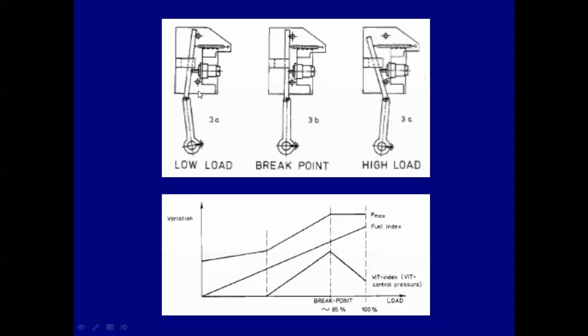So as this button moves in, that is going to advance your timing to a maximum point, and then as it keeps moving, very quickly it's going to go back to its original injection timing.